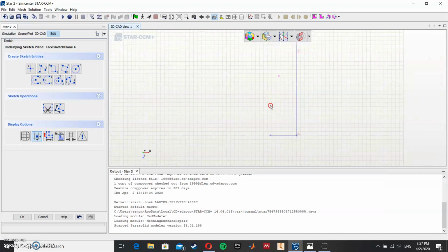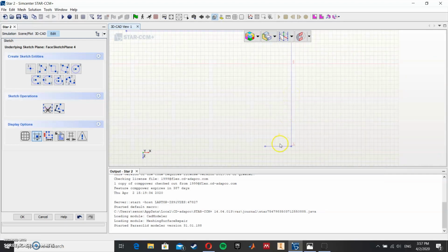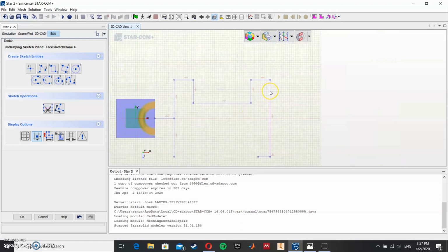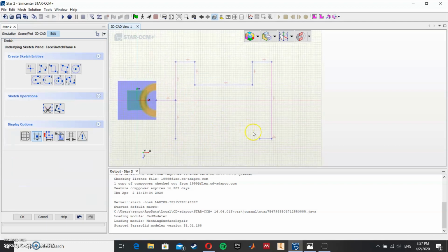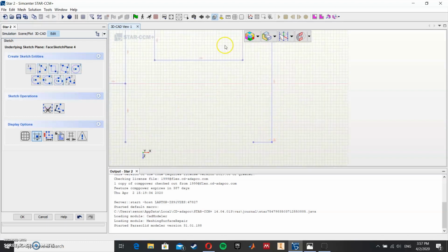And there it is. If this line is changing according to this line, you have to set some fixation points for this line. For example, make these two lines parallel to each other, and this won't move, but this will move since it is not fixated to any other line.